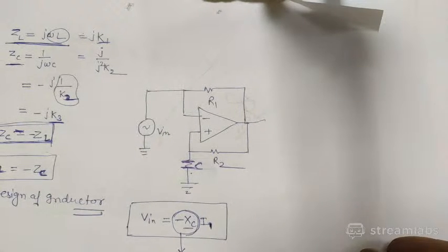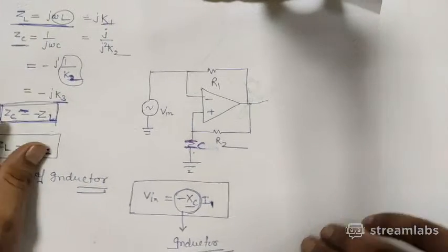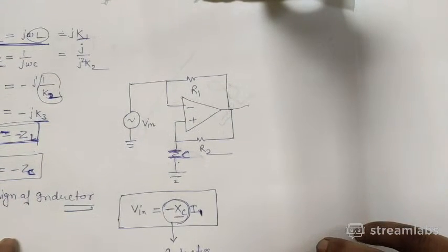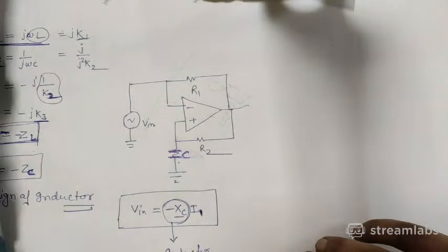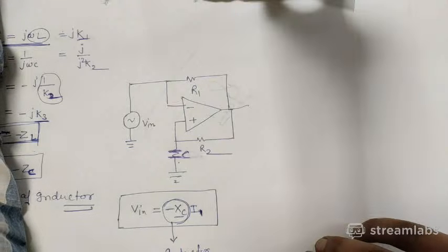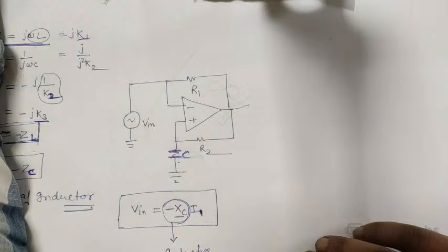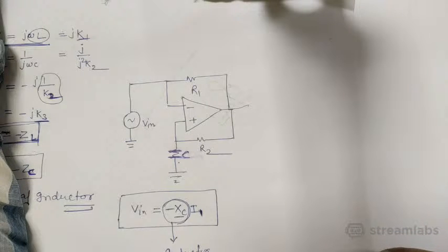This is another application of our NRC circuit, meaning negative resistance circuit, to design an inductor. This is also planned in a separate class, how to design an inductor. Because inductors are big and bulky and can cause electromagnetic interference elsewhere in the circuit, by using the negative impedance converter we make a device that works like an inductor, and we can eliminate those nasty inductances in designs in